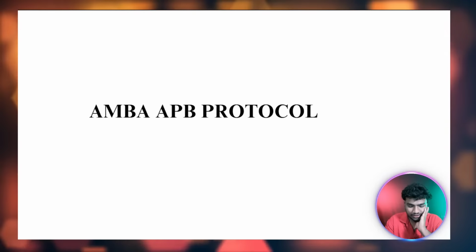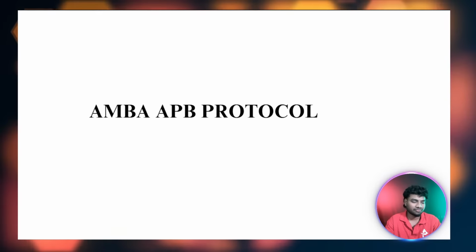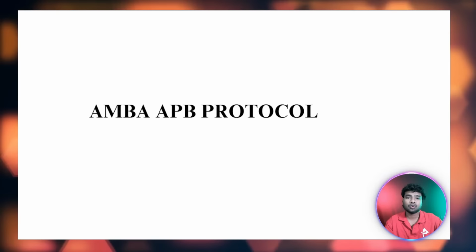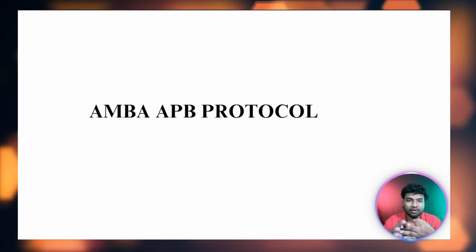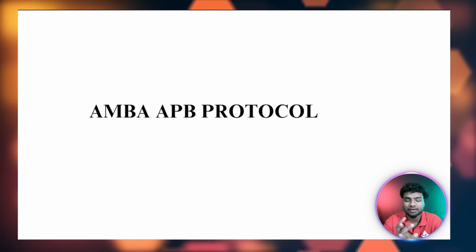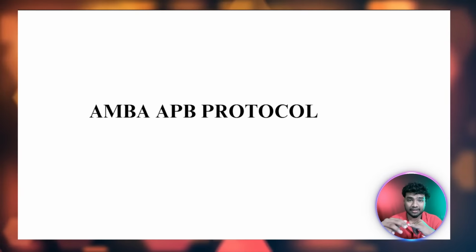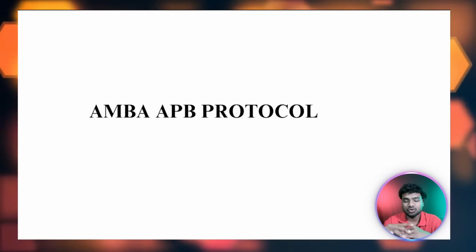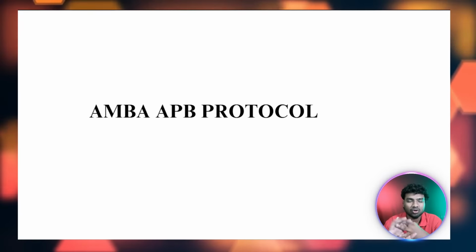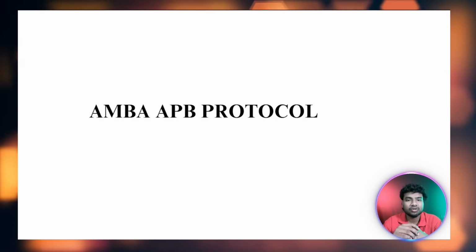Directly we are going to see the coding part of the APB protocol. But before that, let's recall some technical things about it. The main thing is that APB is an on-chip protocol. It needs two clock cycles to make one transfer, and it is based around the PENABLE signal. The P is a prefix of APB because APB comes under the AMBA protocols, which include APB, AXI, and AHB. APB is a low speed, low performance, low bandwidth protocol, mostly used to interface peripheral devices with the chip, and it also has low power consumption.